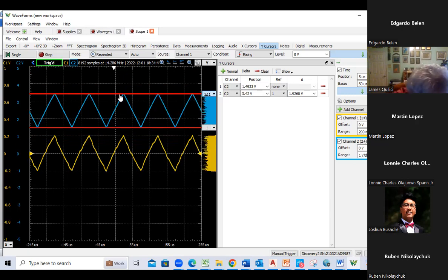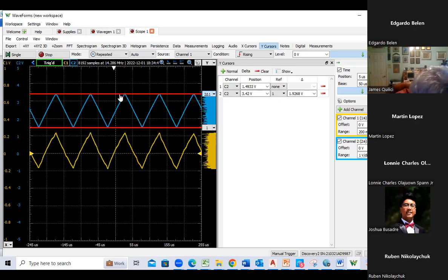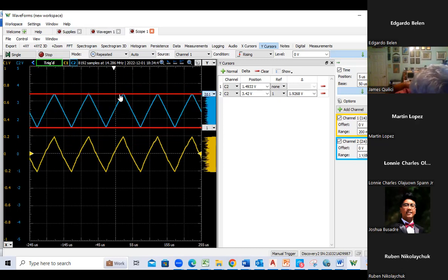Okay. So anyway, finally step 11, it says do a frequency sweep and find the lower minus 3 dB frequency. So we want to find out where the amplifier's high pass, it's on the low end, but it's a high pass, where that occurs.